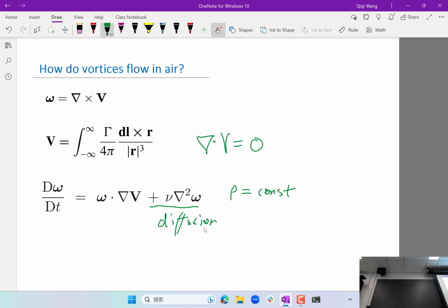It is equivalent to the ratio of conductivity to heat capacitance in a heat equation. So if mu is very small, it is almost like a heat insulator, right? Something that has very poor conductance, or a combination of poor conductance and high heat capacitance.